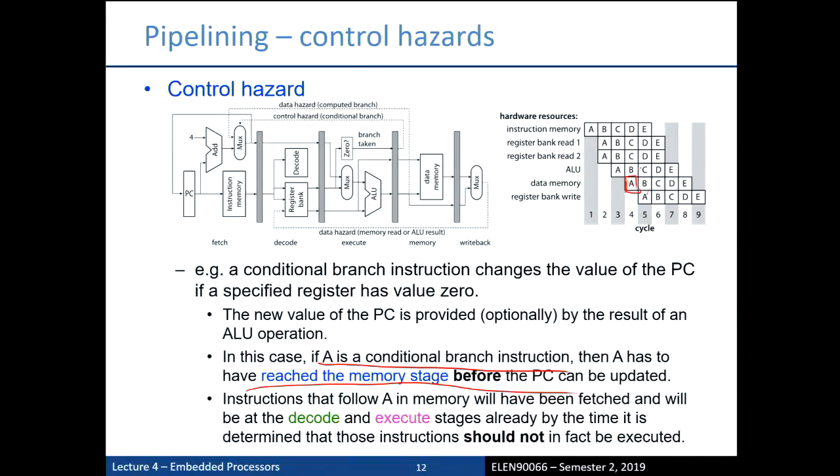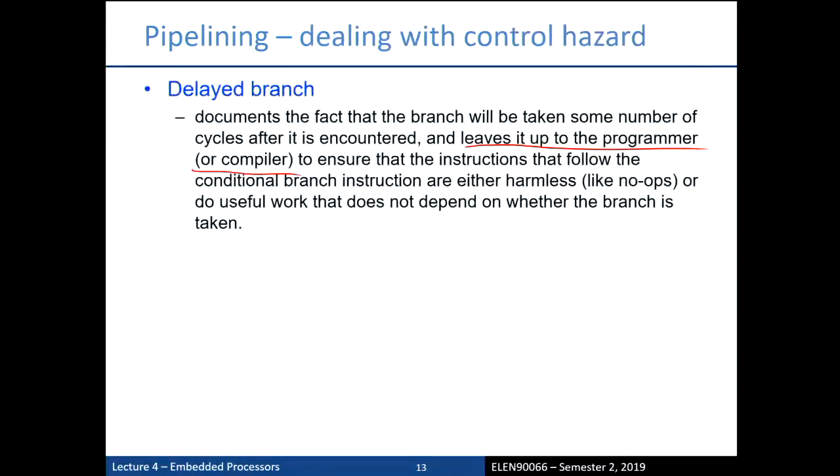Okay, so in other words, if this is a branch, you cannot have these instructions being destructive operations, messing around with the register file, overriding values. Because if you then go and branch to instruction X, which needs those values, you've gone and destroyed them with instructions that should not have run. Ugh, it's a pain. So what do? You basically do what's called a delayed branch. So you either do stuff that doesn't upset the state of the system, so you start padding other instructions in there, or you put good old no ops in there again.